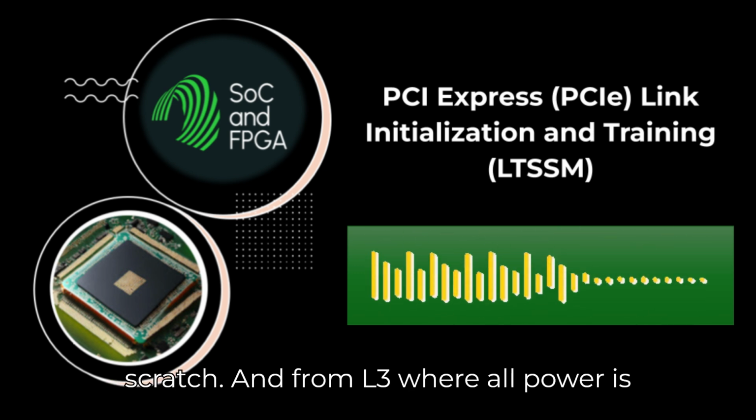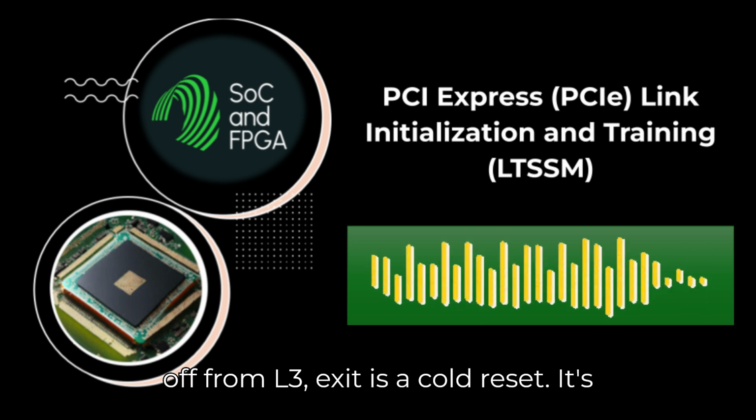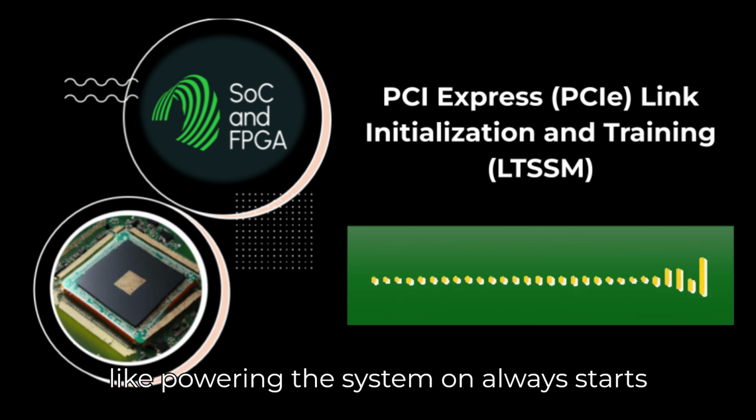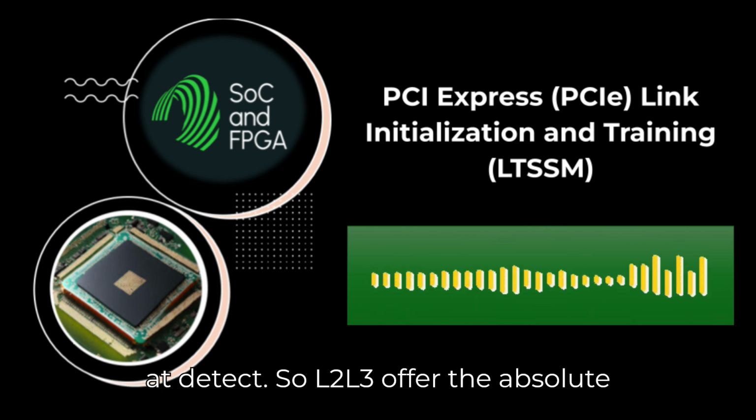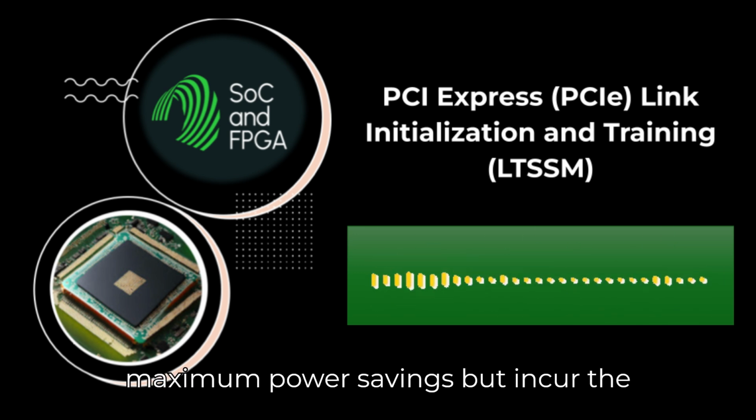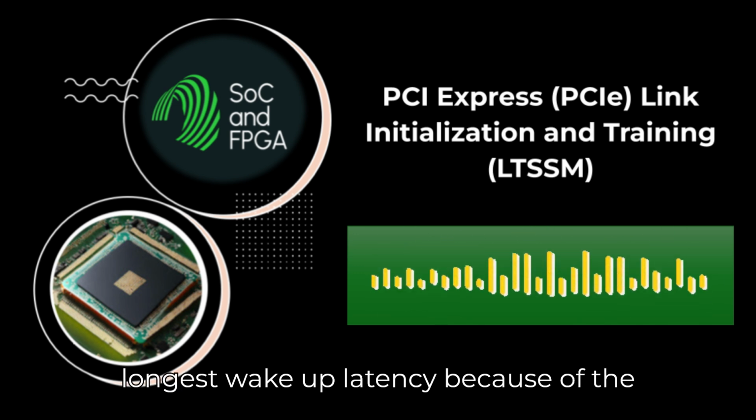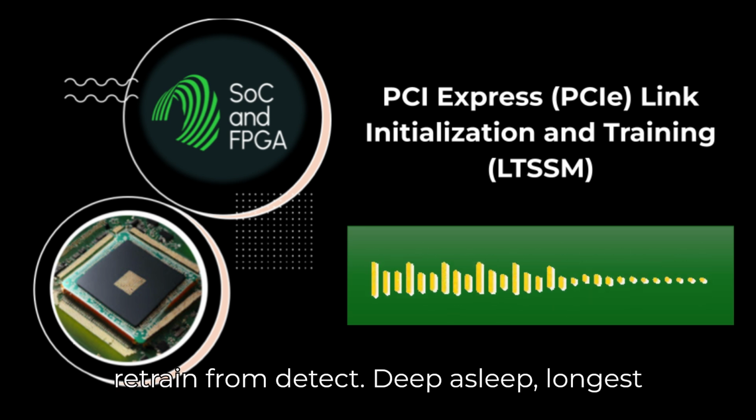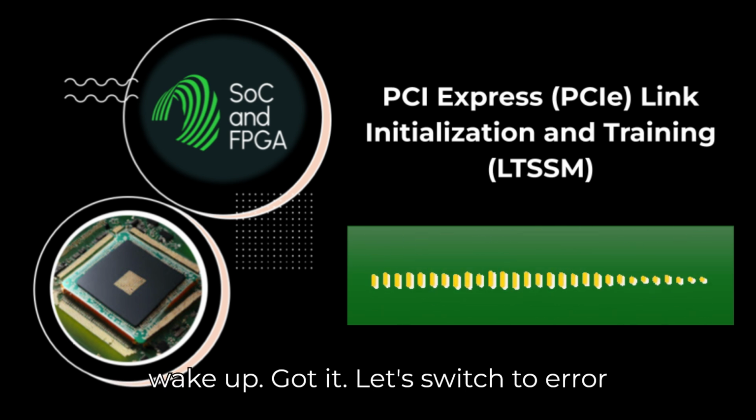And from L3, where all power is off? From L3, exit is a cold reset. It's like powering the system on, always starts at detect. So L2, L3 offer the absolute maximum power savings but incur the longest wake-up latency because of the power restore and the mandatory full retrain from detect. Deepest sleep, longest wake-up. Got it.